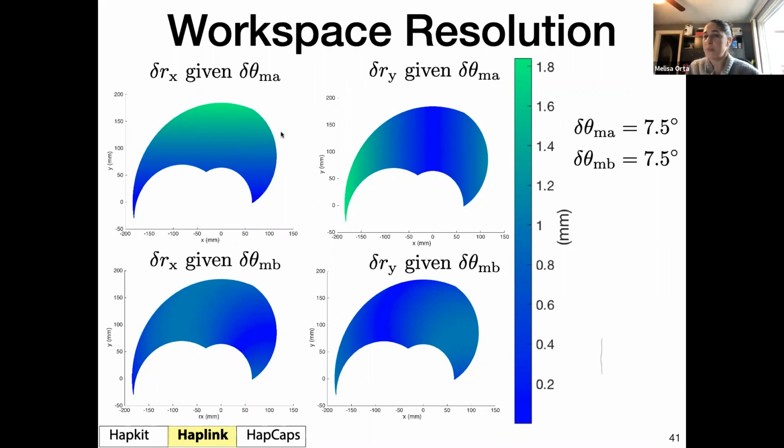In 1 degree of freedom, it's not such a big deal if you don't have your wall at exactly the same place where you had it the first time, or if things shift around a little bit. In 2 degrees of freedom, it is a big deal because the forces are now proportional to where you are in space. So one of the analyses you have to do is to really understand where in the workspace you can render different things.